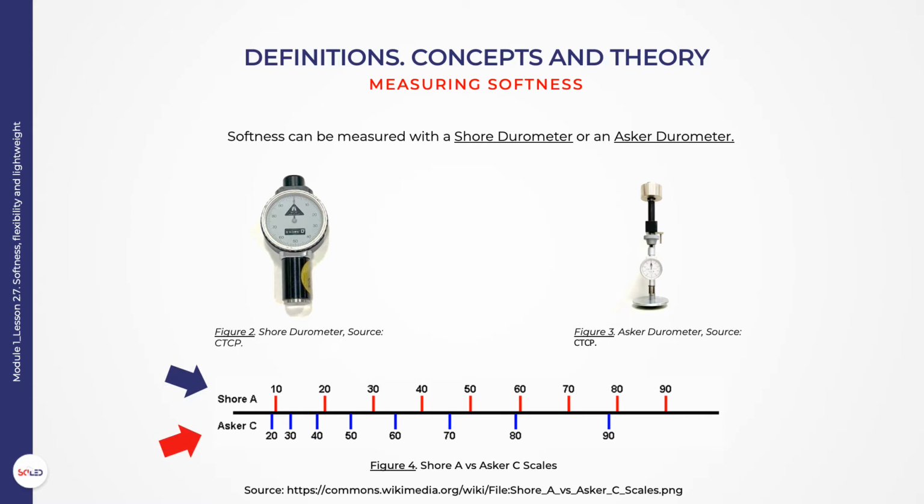The common hardness scales are Shore A, normal rubber; Shore D, hard rubber and plastics; ASKER C, soft rubber; ASKER F, urethane foam, sponge and polystyrene foam. The special hardness scales are ASKER J, normal rubber and softer plastics; ASKER B, semi-rigid rubber and plastics; ASKER C2, soft rubber and sponge; ASKER CS, polystyrene foam; ASKER E, soft and cellular rubber.